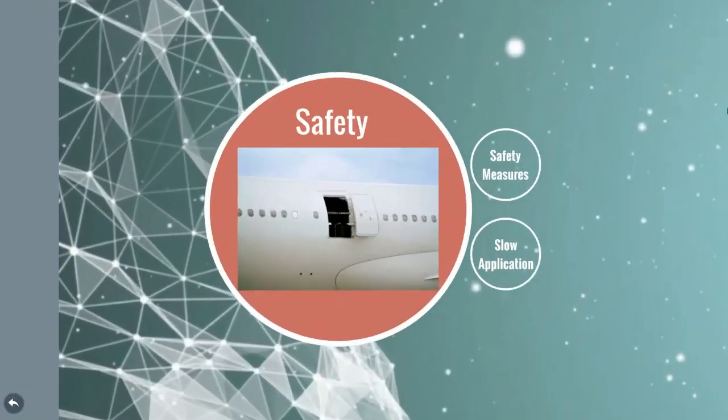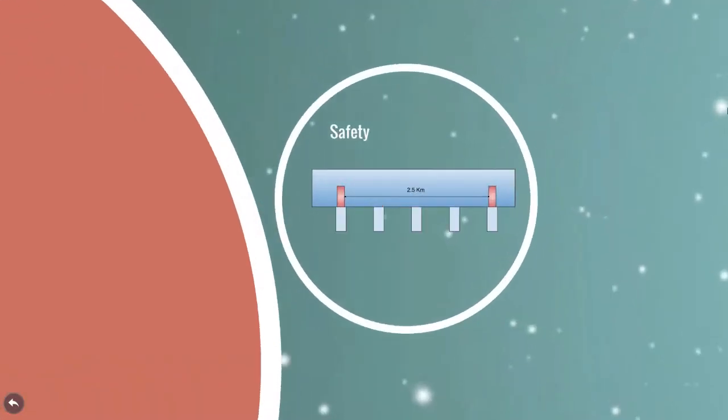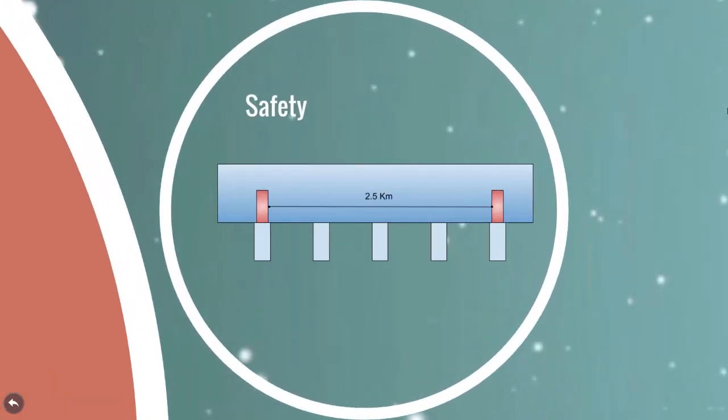Safety. The most important factor of design has to be safety. Within the pod, only straightforward things like an AED, first aid kit, emergency brakes and escape airlocks must be in place. With the use of small algorithms, pods can be controlled for braking to prevent collision and emergency services can be automatically informed. At every 2.5 kilometers, an emergency exit is constructed on the tube for people to get out.